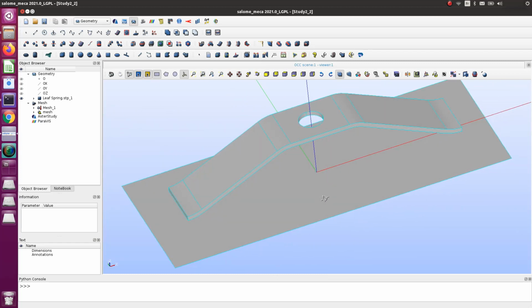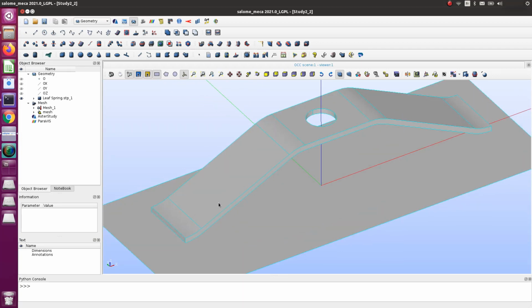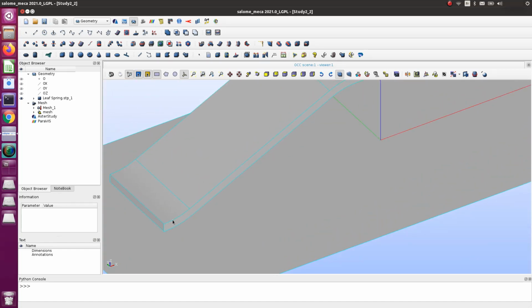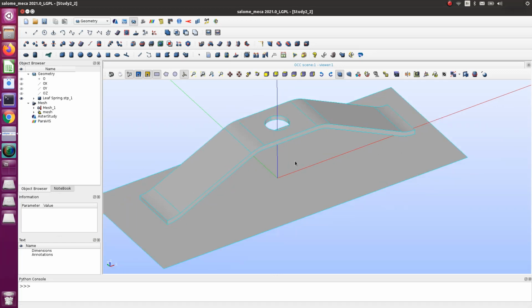Now finally, I want this model to have a very good mesh. I like to mesh it with hexa elements, and the way it is constructed right now, if you look at those areas here, there's just a line here. It's not in here. It's a full solid. So basically, it's not a block. So I have to divide this into a block or several blocks, so I'm able to use the hexa mesher and split that into a hexa mesh. It's also very thin, so controlling the number of elements on the thickness will not be easy.